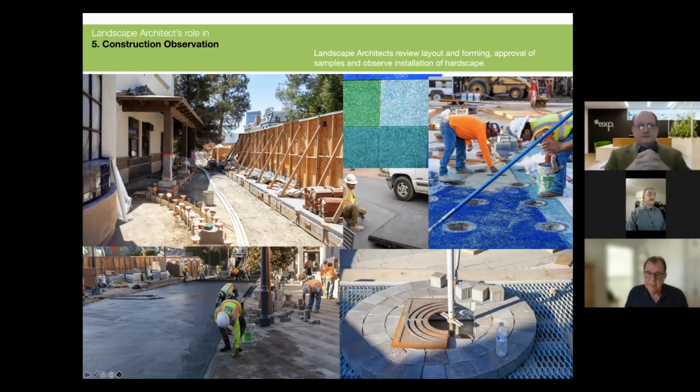I might mention that after we did this install, we learned that because of the volume of pressure washing and the way the maintenance crews did that, they were putting too much water into the tree. And so that grate on the top was changed to eliminate the spaces that you see, and then add a collar along the top to prevent water from running into the tree root ball.